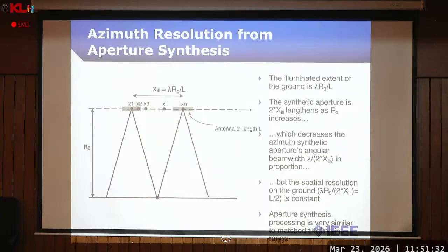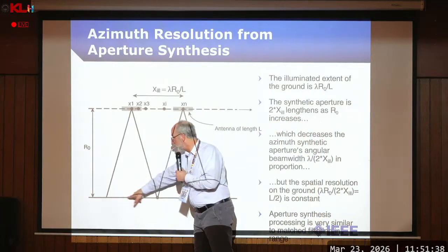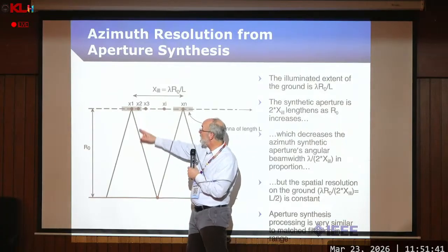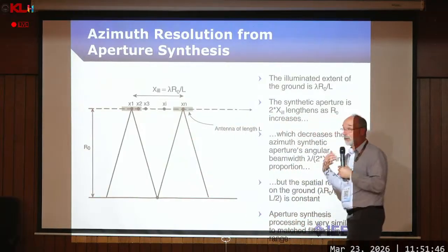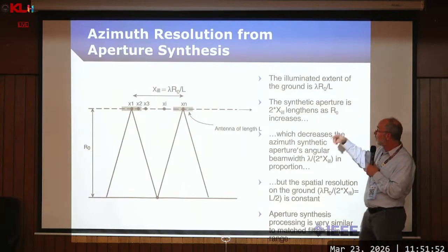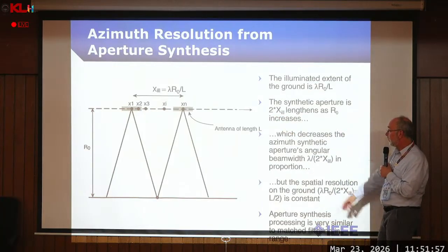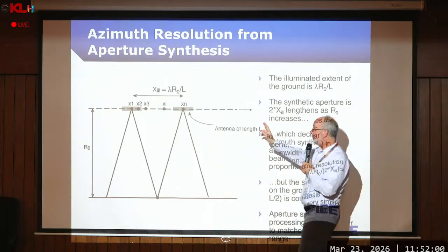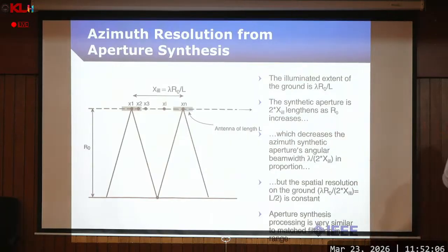Another way of looking at the synthetic aperture is as though we are flying along, we image a wide area, and our point on the ground is imaged over many points as we fly along. And those antenna points can then be considered as the synthetic aperture because of two-way propagation. It's basically twice the illumination distance. And by essentially assuming that these are all observations on a particular aperture, correcting the phase for that range distance, and then summing them all up, you get the high resolution.